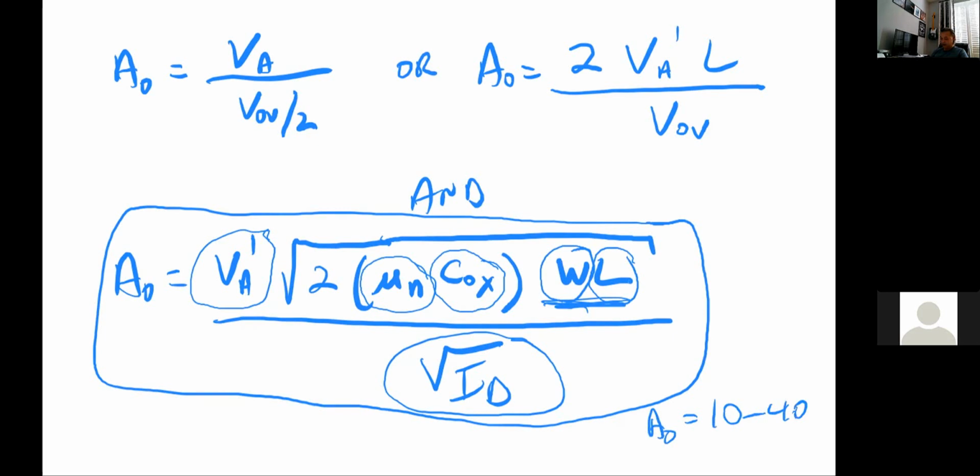And when we actually build an op-amp, you can have multiple stages of this basic gain cell or better modified gain cells that we'll see later. But you can see how we can get to that maybe more than 10,000 type of open loop gain that op-amps have.